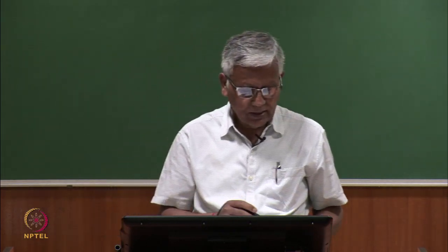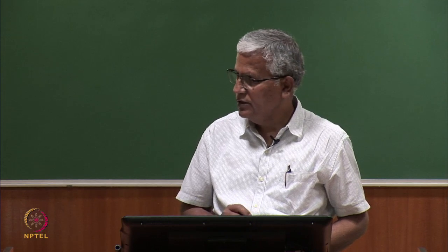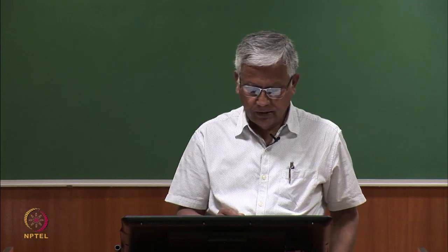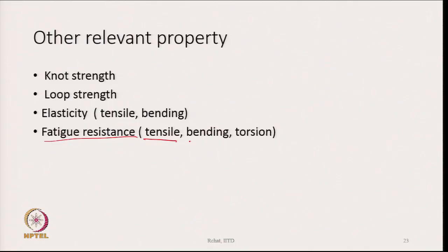These are important. Similarly, fatigue resistance is also important. It could be tensile fatigue, bending fatigue, and torsional fatigue. So, depending upon the end use, fatigue resistance is important in the case of, let us say, tire cord.